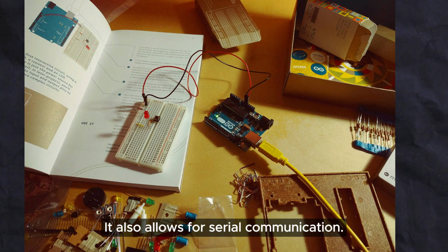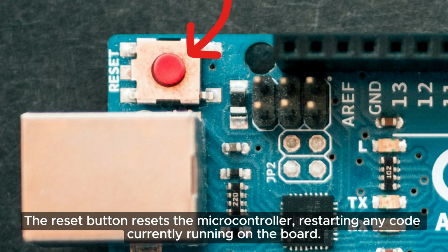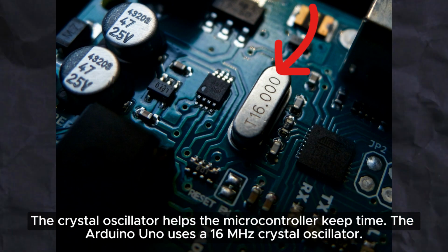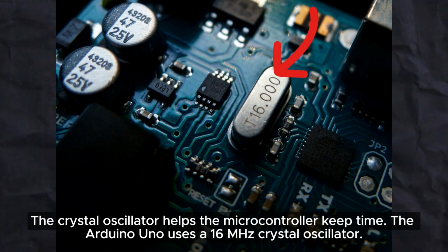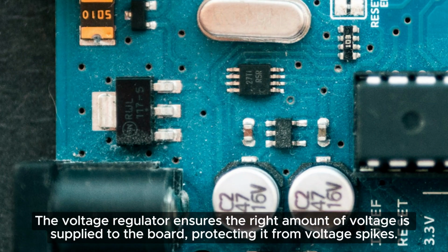The reset button resets the microcontroller, restarting any code currently running on the board. The crystal oscillator helps the microcontroller keep time. The Arduino Uno uses a 16 MHz crystal oscillator. The voltage regulator ensures the right amount of voltage is supplied to the board, protecting it from voltage spikes.